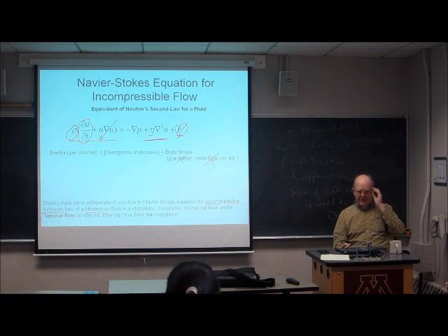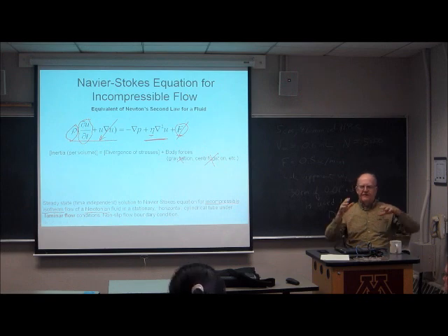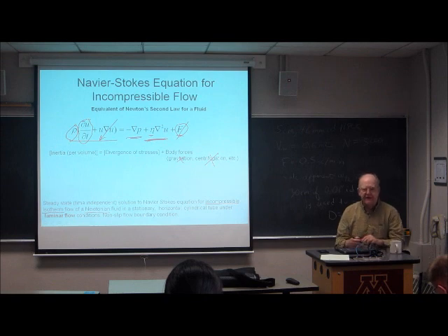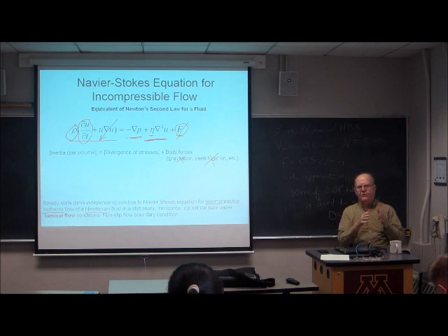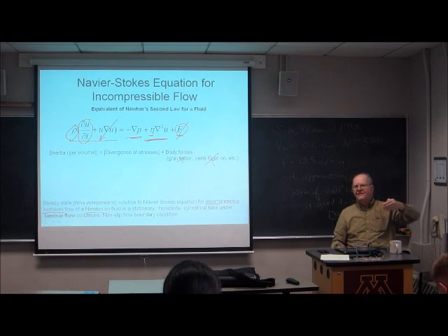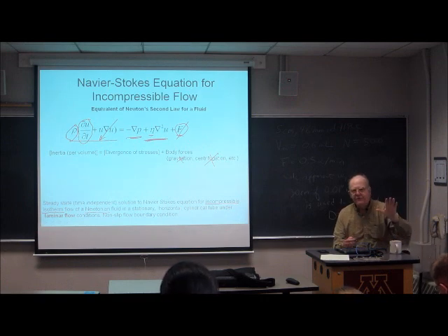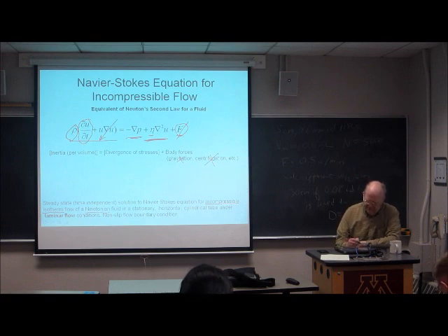Say it again. Under laminar flow conditions, all of the inertial factors don't amount to anything compared to the viscous factors and the pressure that you apply to the fluid. So it is the pressure that you apply that makes the fluid flow in the horizontal tube. If you had a vertical tube, it could, of course, under the force of gravity, induce flow. We're going to get rid of that factor. We don't need to worry about it in the problems we're interested in.